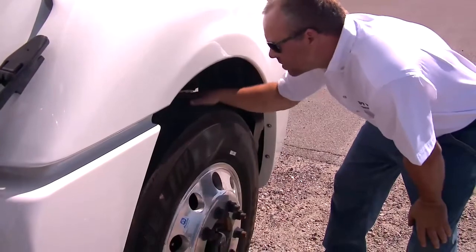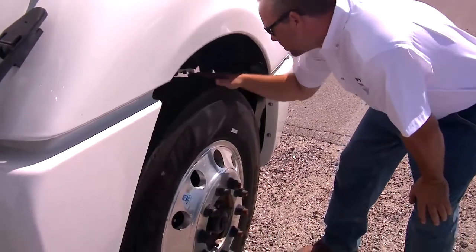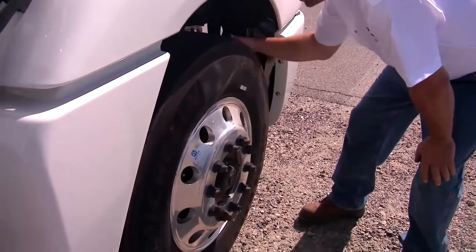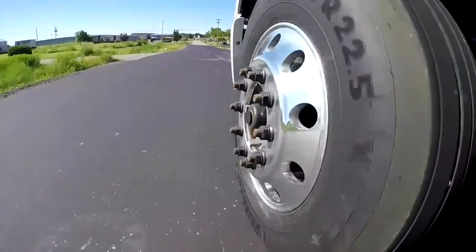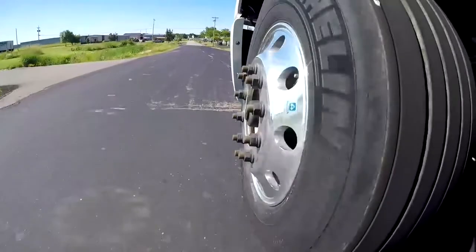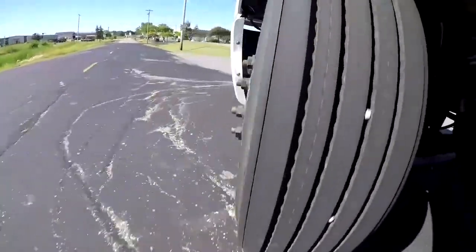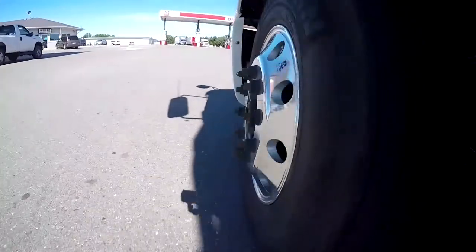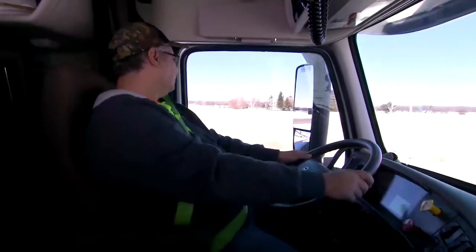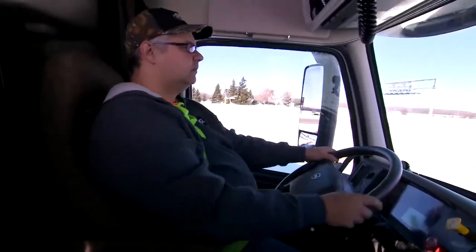Tires are a major expense for trucking companies, and like we mentioned before, underinflation is the #1 cause of tire problems. When tire pressure is down 10 to 20%, tires will start to show strange wear patterns. And at 20% or more pressure loss, the risk of a sidewall blowout increases tremendously. If that tire blows while you're en route, you've got problems.